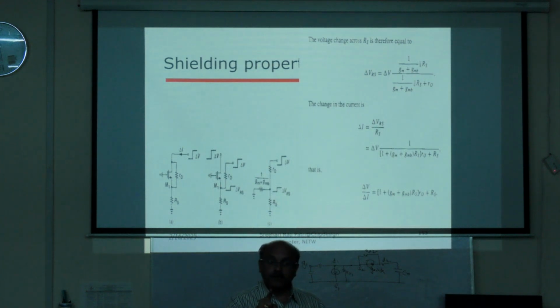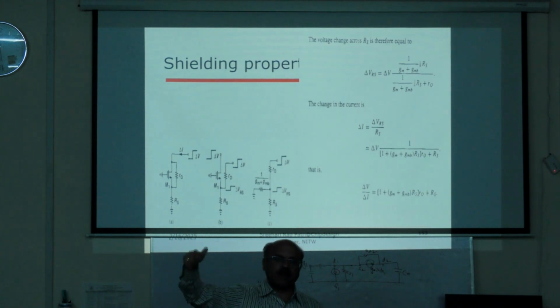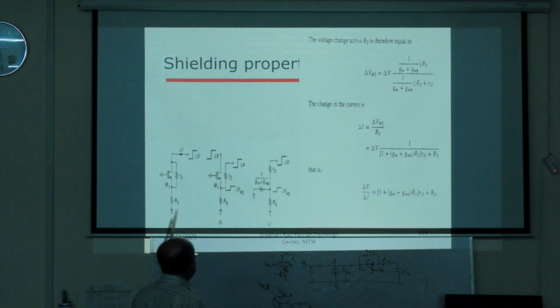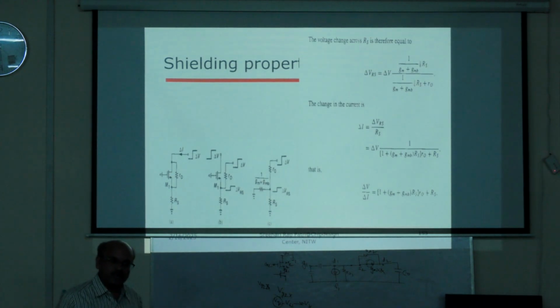Now what is it I am doing? I am evaluating the output impedance. When I am going to evaluate the output impedance for any circuit, I will mute the input signal, apply some voltage at the output node, and try to evaluate dVd by dId, that is the output impedance, right? So here also, when I try to do that for the cascode, you are muting the bottom transistor, the driving transistor. When you do that, it is just like a resistor. So then it just mimics that. And how about the upper transistor? Anyhow its gate is a DC voltage, that is always ground only, right?